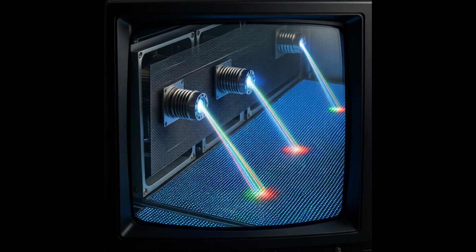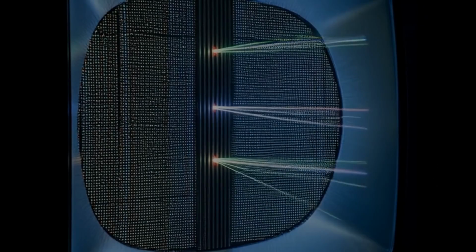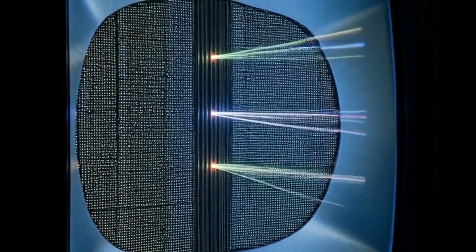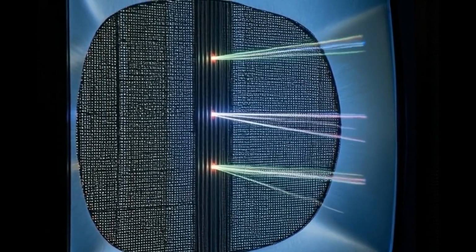To ensure each electron beam strikes only its designated color, a perforated metal shadow mask sits just behind the glass faceplate, acting as a physical alignment guide for 3 separate electron streams. As the beams pass through specific holes in this mask, they converge at exact points on the phosphor layer so that red electrons excite only red dots, while green and blue remain isolated from their counterparts.